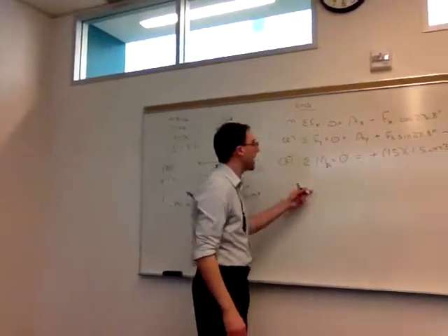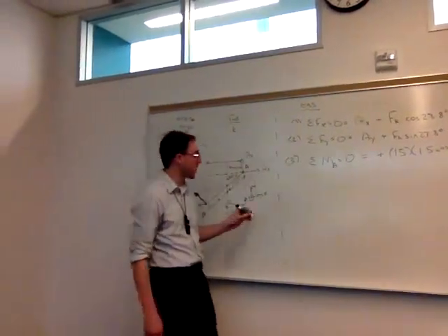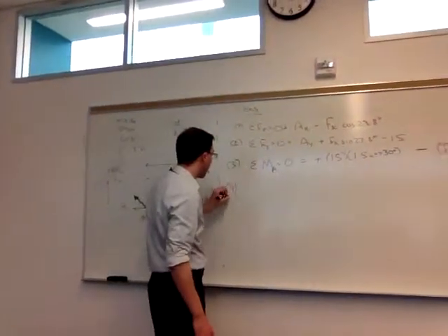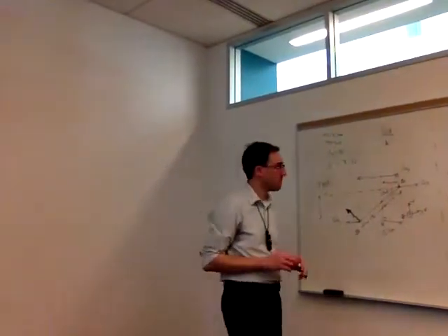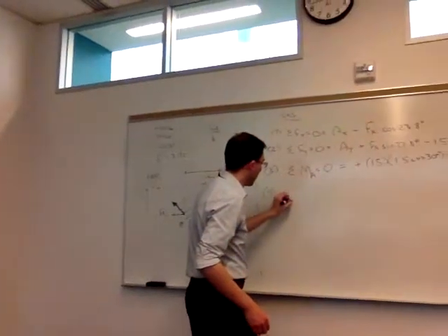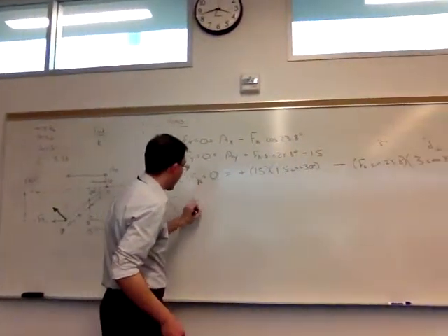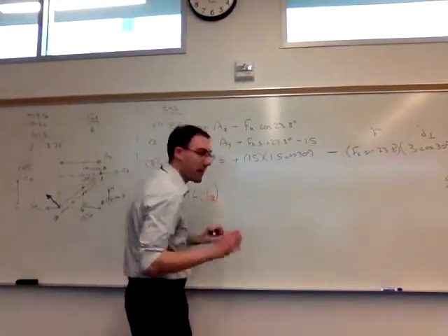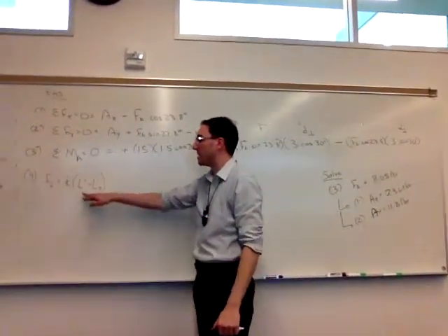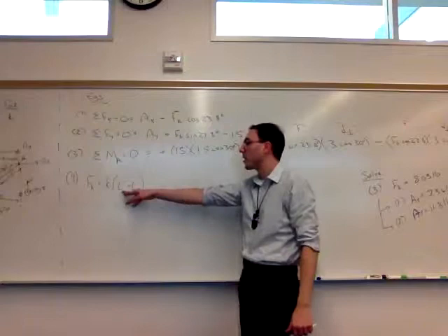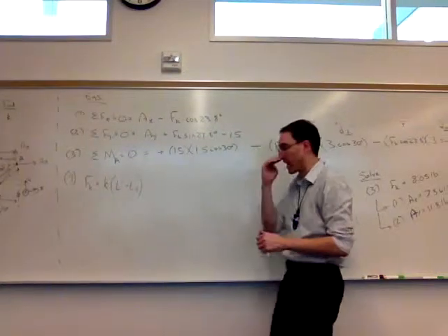Right, so now we have to come back to the step because we still don't know what K is. So what's our fourth equation, at least in terms of variables? Right, so we can use this formulation of Hooke's law. So again, we're assuming tension. So the force in the spring is the spring constant times the quantity equilibrium length minus unstretched length.